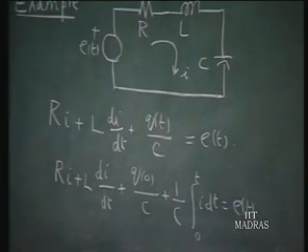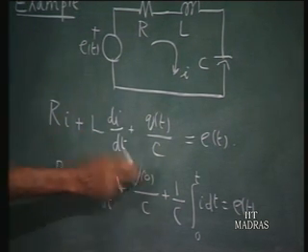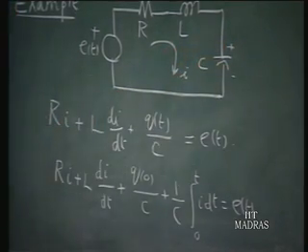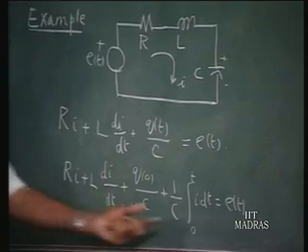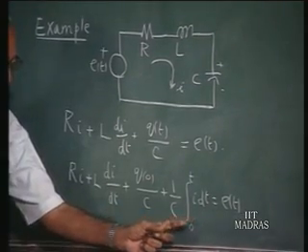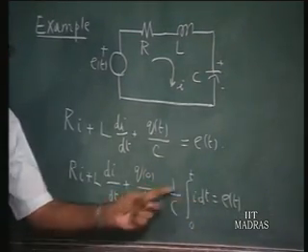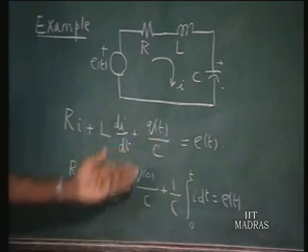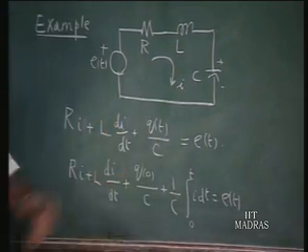So what I have done here is, Q of t has been thought of as comprising two parts. One is the initial charge on the capacitor, with this plate as positive and this as negative, and the additional charge that has been put on the capacitor plates in the interval 0 to t, integral i dt divided by C. So Q0 plus the additional charge, divided by C, the expression for Q of t by C, is broken up into these two parts.